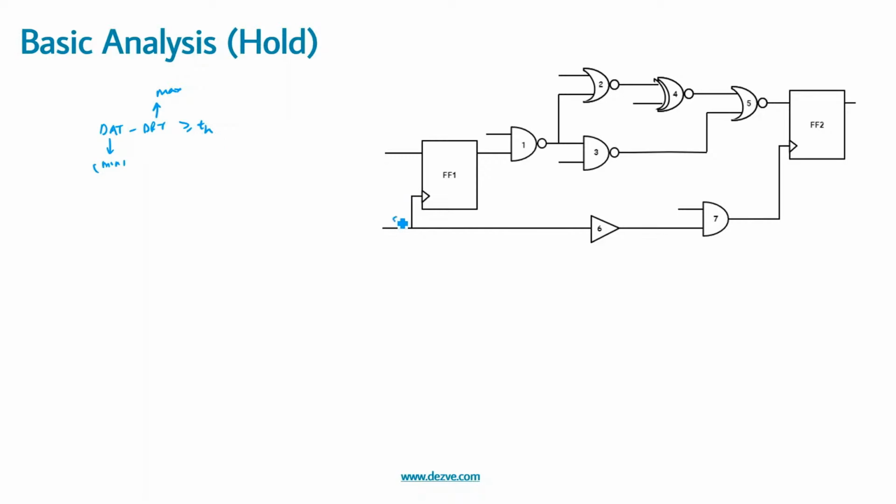In this case, this is segment 1, segment 2, clock to Q. Again, the shortest path, the minimum path, would be via this path, correct? So the DAT would be segment 1 plus segment 2 plus T clock to Q delay plus C1 plus C3 plus C5, correct?